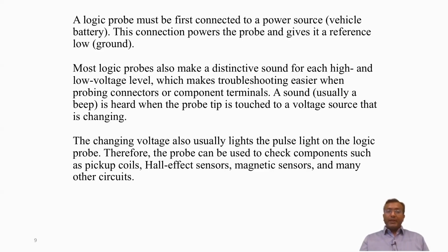A logic probe helps to check components that should alternate between high and low voltage. For example, when testing a crankshaft position sensor, the logic probe can show the pulse generated as the crankshaft rotates. A working sensor will produce a regular signal, helping to confirm its functionality.